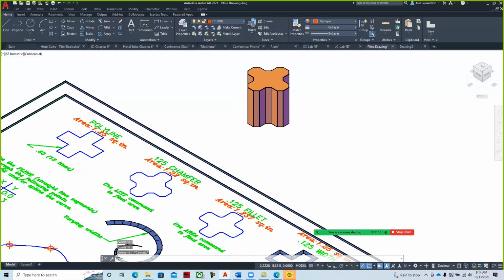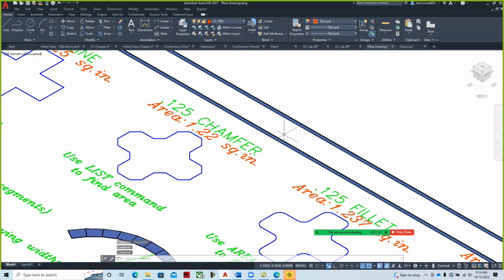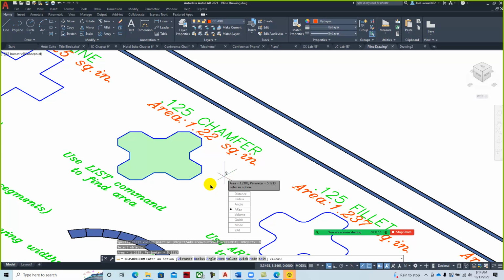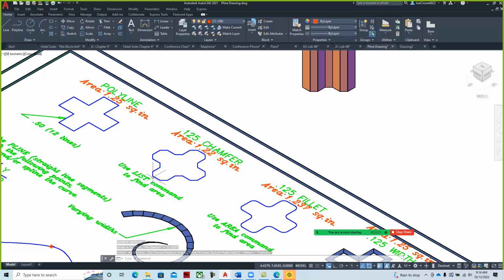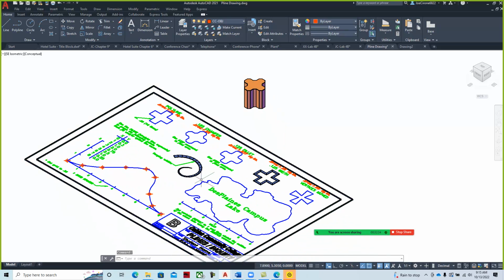The other thing we can do with them is we can calculate the area on them. And so if we were going to go to our drawing utilities and look at things like the area, we can calculate the area of an object by clicking on it. And so it tells us the area is 1.2188, depending on how many decimal places of accuracy we're working on with that. And that's a very useful tool because we can have these polygon type shapes and calculate out the area, which we could use for things like calculating out square feet for carpeting or wood flooring or other applications as we go into CAD.